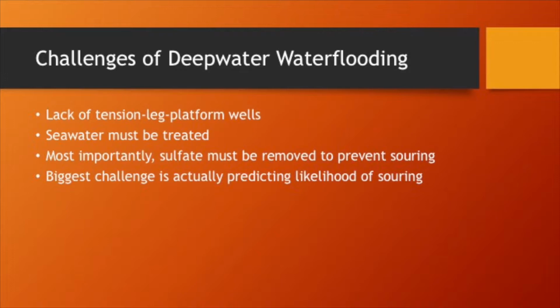Another issue is that seawater needs to be treated before injection. Lack of treatment can cause issues such as oxygen corrosion, biofouling, microbial-induced corrosion, injectivity problems, reservoir souring, and barite scaling. One fix for the particulate and oxygen levels is putting the water intake at an optimum depth so as to limit those factors. Another issue is organisms that cause biofouling, which creates a biofilm that is corrosive.